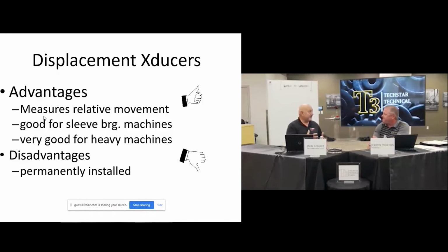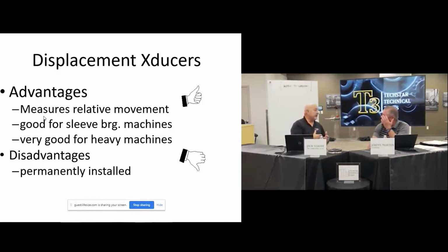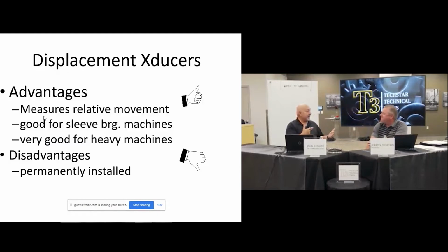That's right. I mean, the driver, the transmitter, all of this could have some type of issue with it. And I get called a lot of times to come out because they're having some type of issue. Just for instance, on this one machine, they set the probes at the factory, but they set them for the machine to be shipped, so they back them out so there's no contact. But they're still within the gap range, but the gap range may be like negative 17 volts or something like that. You're right on the very edge of the curve.